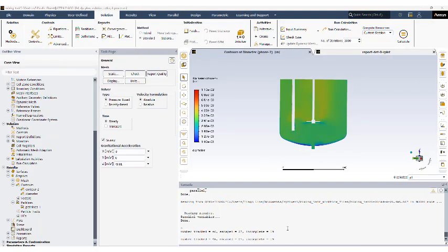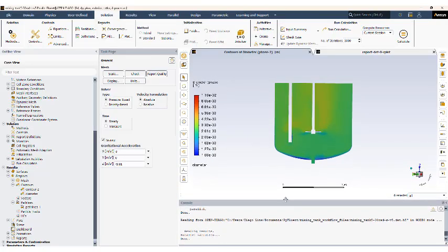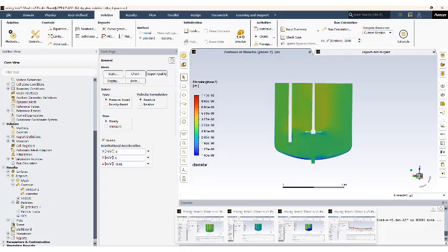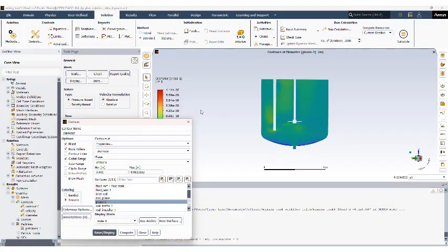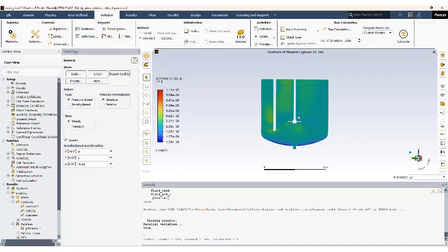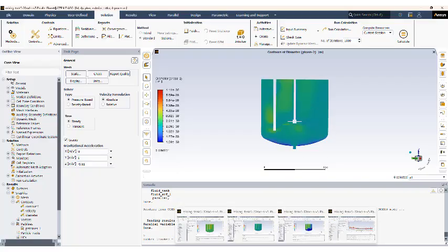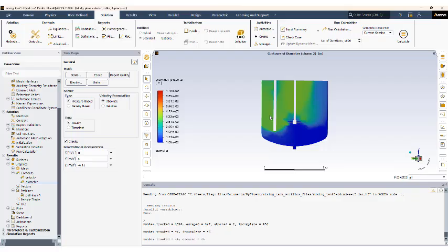I also want to briefly talk about comparing the diameter distribution of the bubbles for the different cases. So basically, what we have here is the profile, the contours. We can compare 30 radians per second with 20 radians per second. Again, it's a bit darker green, indicating that it seems to have smaller bubbles. And if you go with 10 radians per second, you actually get a lot more concentrated plume of bubbles basically moving upwards. So usually, the bigger the bubble, the faster they go up.